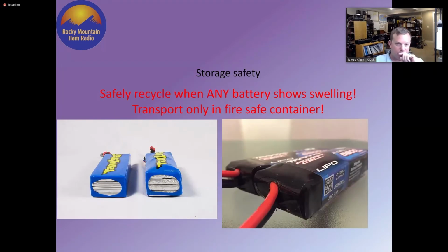Now, remember I said most of the lithium batteries are not in hard cases, though. This is a very typical radio control battery where it's just shrink wrapped. Everything is soft. If your battery is swelling in any way, shape, or form, please transport it and recycle it safely. Don't use it. That battery is going to fail. With that battery, you are asking for trouble. If that battery shows any swelling like that, it is going to fail, and it could very well fail catastrophically with fire or explosion.